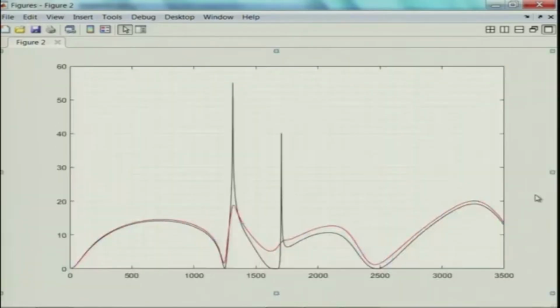So you get this kind of a red colored curve, but the point I am trying to make is that these black and red curves are nearly the same in the low frequency, and qualitatively they remain the same as we go to the higher frequency range, and of course there is a limit up to which plane waves are there. Deviations will happen as the mean flow approaches a non-zero value.